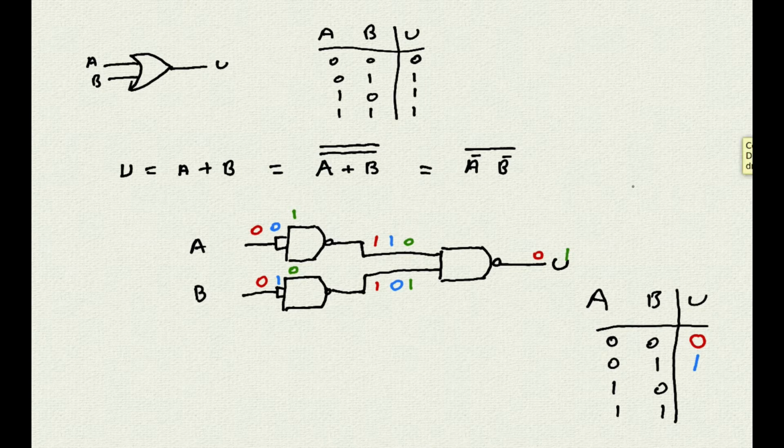Yeah, I just realized I forgot to write down on the circuit the previous output. Here, fixed. Now, let's see what happens with the last row, for which we need to input two 1s into the circuit. The two 1s become both a 0, and the two zeros are applied to the final NAND gate, which of course will output a 1.